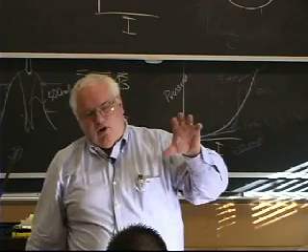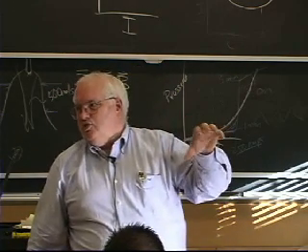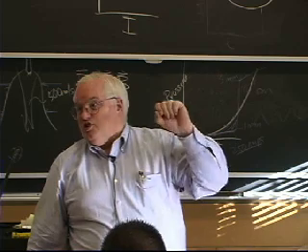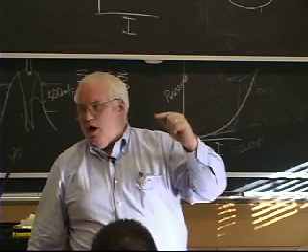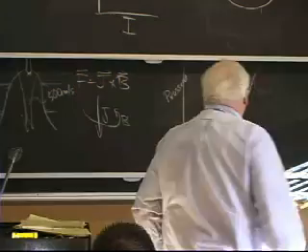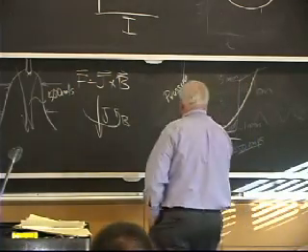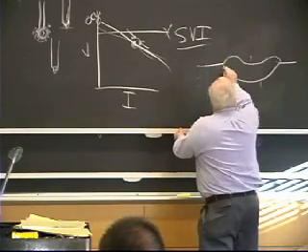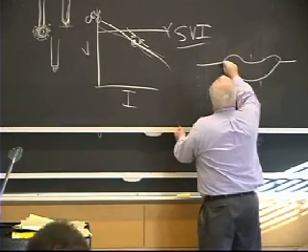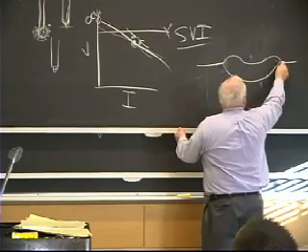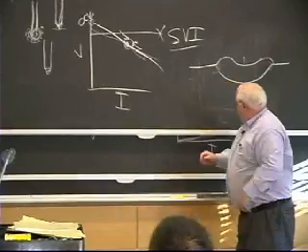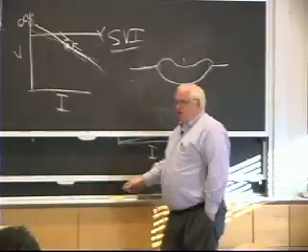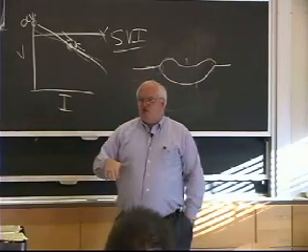Well, if that stuff starts getting into the solidification range of the weld pool, I start producing undercutting, which is a little notch at the side of the weld bead. Okay, an undercut would show up as a little depression right here. Well, actually, it's going to end up showing up right here, where I basically freeze in part of the wake where I have a depression.